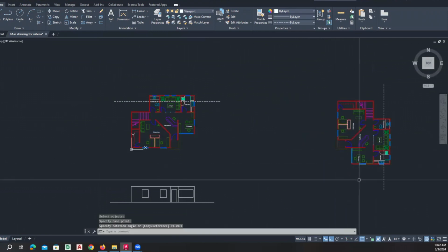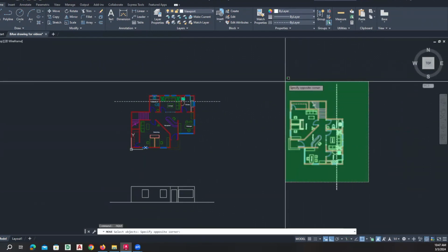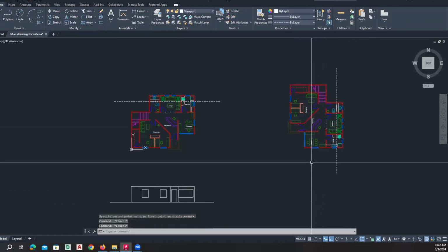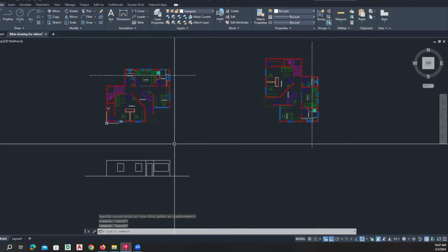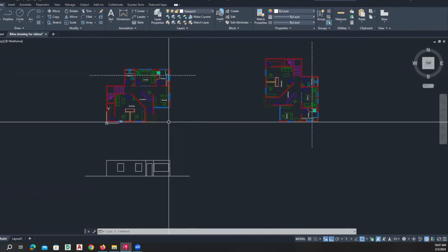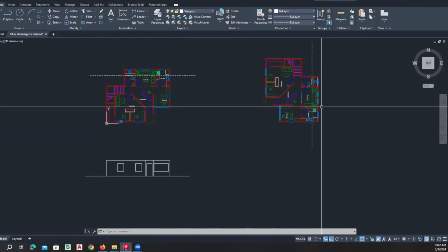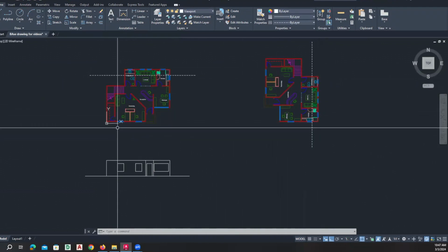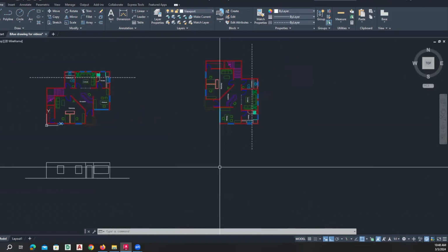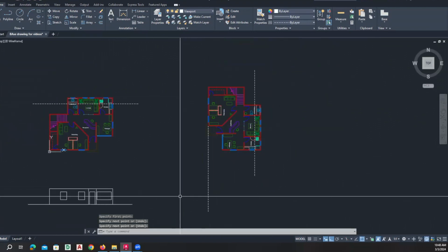90 degrees so that the east side is now facing, it's aligned with the X and Y axis, right? So normally the east side would have been aligned with your Y axis. Now that we rotated our plan, the east side is now parallel to the X axis, okay? And if we were to do this, it would be very similar. We would project all the lines from the corners, just as we did before.